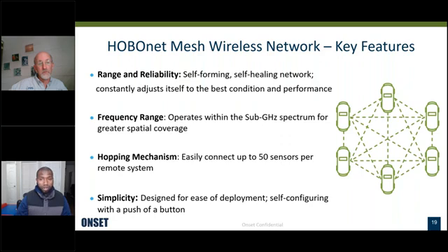With this technology, we went with the sub-gigahertz frequency range, and what it does is offer you better penetration through obstacles. Obviously, any type of water and metals tend to absorb frequencies, so your transmission range can get a little bit limited. The sub-gigahertz range is not immune to that, but at least it allows you to travel longer ranges and also penetrate through obstacles a bit better.